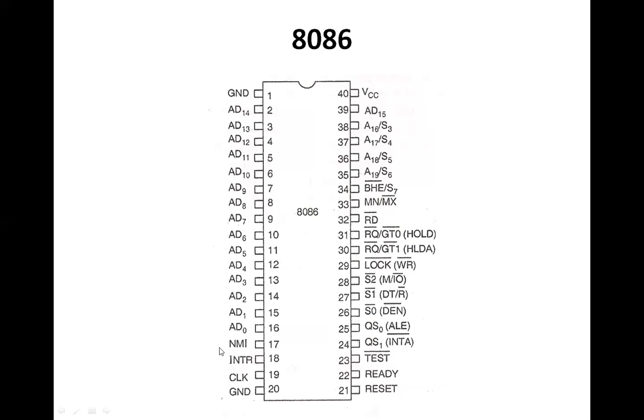But whenever any signal comes into the NMI, the non-maskable interrupt, it has to entertain it. So when the NMI is activated, this interrupt uses interrupt vector 2. Now there are many vectors which can be used for that. INTR is a general one, and NMI is